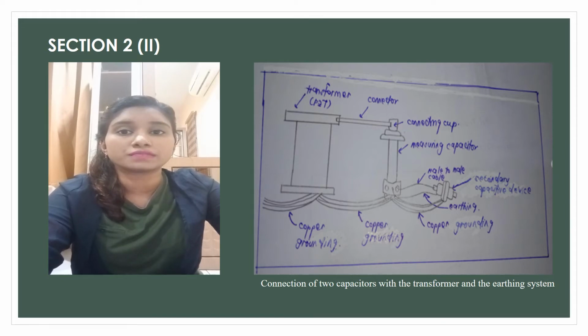The measured capacitor value is 1.09036 microfarad, and the rated voltage is 7 volts RMS, which means that the coaxial cable can only sustain 7 VRMS. The rated capacitance is 2 microfarad. The serial number of the capacitor that we have used is 223410760-04, and the number of capacitances inside is 20, the divider ratio is 2000:1, and the rated frequency is in the range of 10 Hz to 400 Hz.